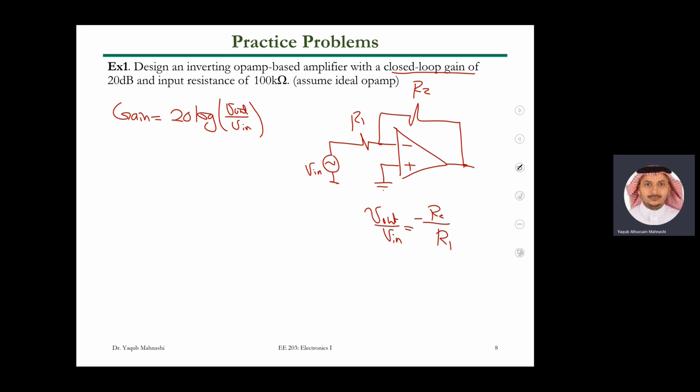Okay, that's the point. So you want to compress that kind of thing. So now you are going from 0 to maybe 1 million, and in dB you are going from how much? Let's say 20 dB until 120 dB. So 120 dB is actually to the power 6, because each 20 dB gives you one power of 10. 20 is 1, 40 is 2, 60 is 3, and so on. Okay. How about 10 dB? If 20 dB is 10 volts per volt, how much will 10 dB give you? Square root of 10.